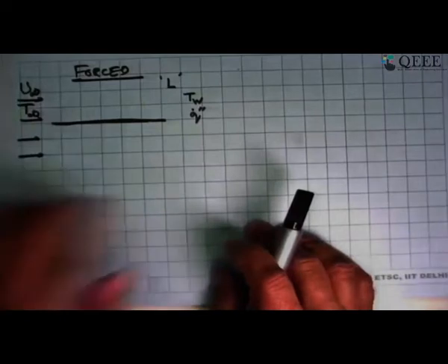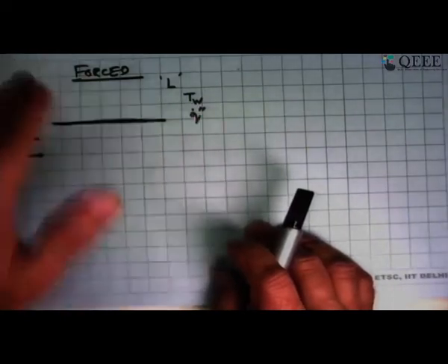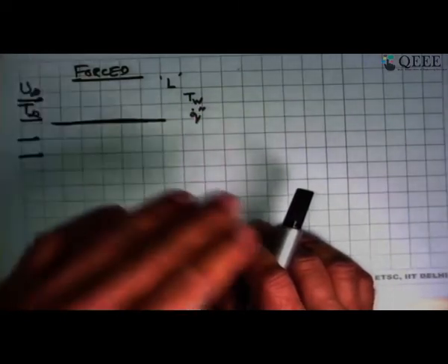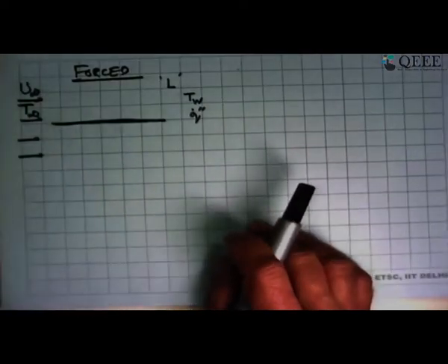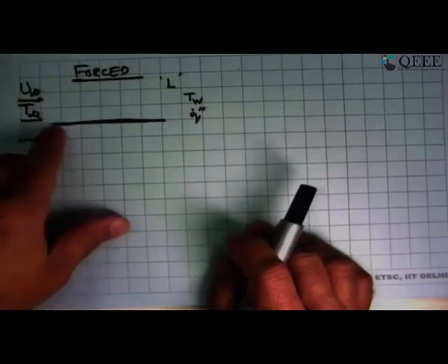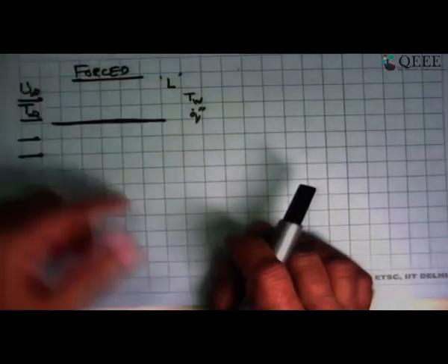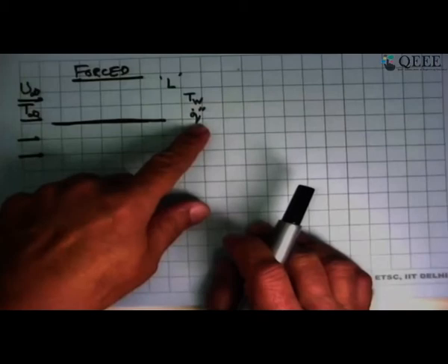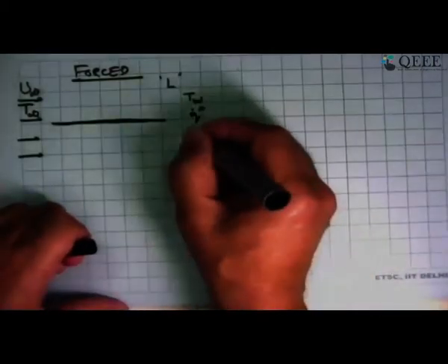In practice, Q dot double prime is what we get when we apply an electric heater. If you have an electric wire with constant resistance and a current flowing, the I squared R heat generation in the wire is constant. So the same thing will happen with a foil or a plate. That's how we can generate a constant heat flux wall, and that we call iso heat flux.